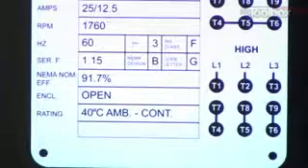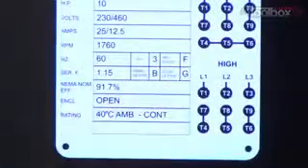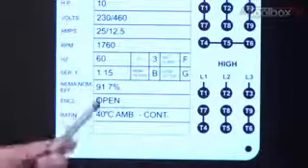The NEMA design, you can find this information on NEMA's website, National Electrical Manufacturers Association, NEMA.org. The design B tells you what type of starting current, what kind of torque, what kind of slip this motor might have. So if you're replacing this motor, make sure that these numbers are the same. The code letter over here, G, refers to the locked rotor kVA. That's kind of a thing engineers would care about when sizing this motor and also sizing other things feeding this motor. Not something maintenance folks have to worry too much about.